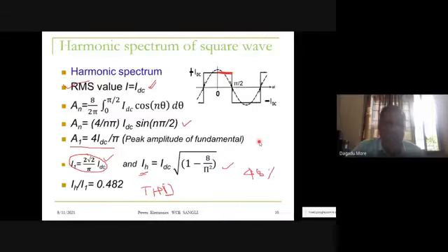We discussed the single phase diode bridge, and our very important conclusion is that the source current of a diode bridge depends upon the type of load on it. For R load, the source current is sinusoidal.